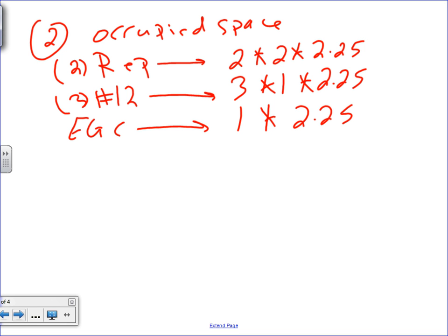That's easy. First, you find the receptacle, 2 allowances based on the largest. All the grounds count as 1. All the conductors count as 1 based on that. Each one of them will count as 1. If I did my math right, and I'm questioning my math after all this driving, as you guys said, 18? Can you guys check this number? 18? Okay.